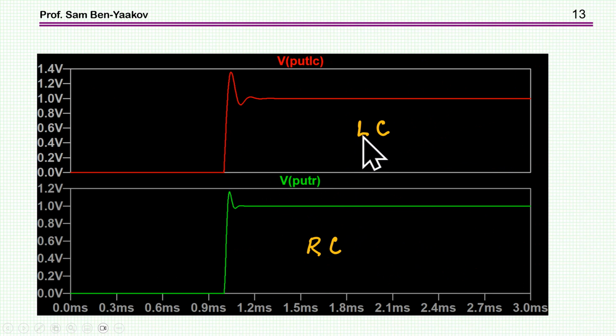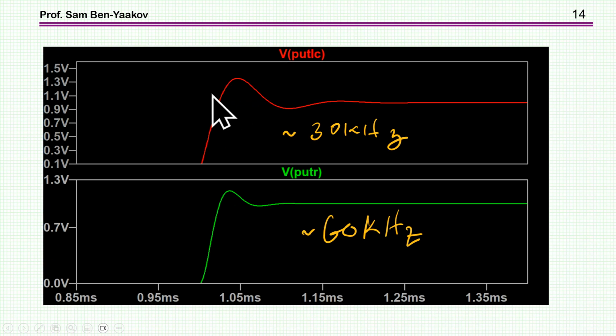And again, the phase margin of the LC circuit is somewhat smaller, so therefore you expect a much higher overshoot. But you might say that the behavior is really very similar. And also, if you look at the frequency of oscillation, then there is a factor of 2. But again, it's reasonable, and that's pretty good as far as we are concerned here, the first order, just for demonstration.